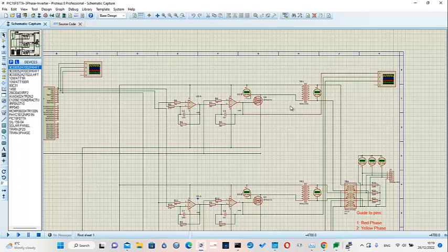So, for each phase, as well as the filter circuit, you will also see a step-up transformer where we convert high current and low voltage to higher voltage and lower current. This demonstration design with one power transistor will output enough power to have 1 amp per phase at 230 volts root mean square.